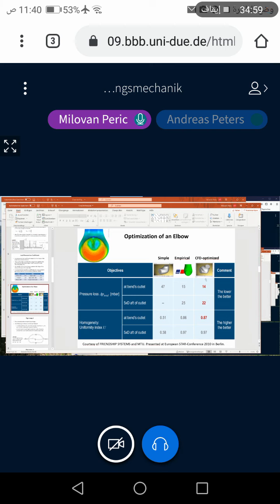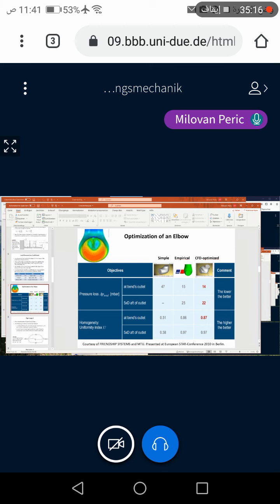I think it was liquid, and I'm not sure whether the cross-sectional area gets larger, but it gets elliptical and it is squeezed. So basically what you achieve is that you go from a circle to an ellipse, which has a very large ratio of the long to the short leg, and this is why there is no strong recirculation, because the recirculation would happen in the cross-sectional area.